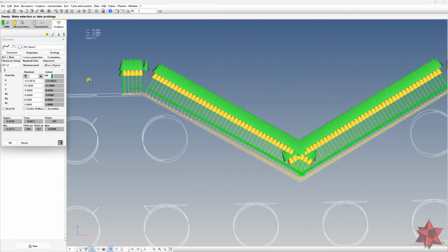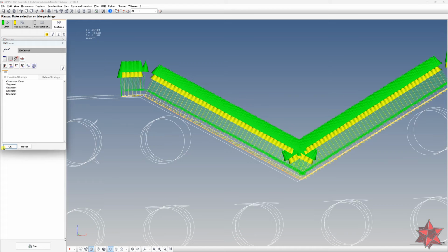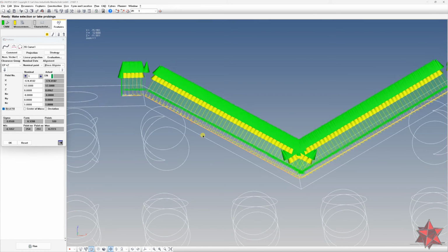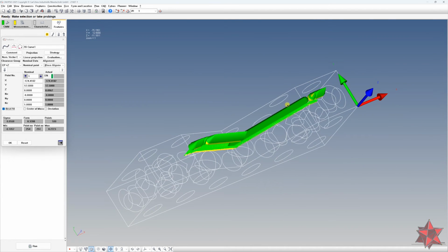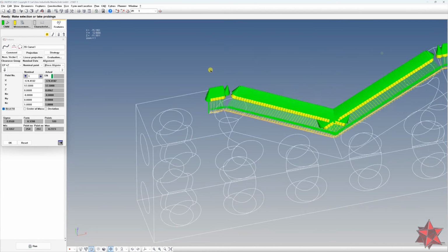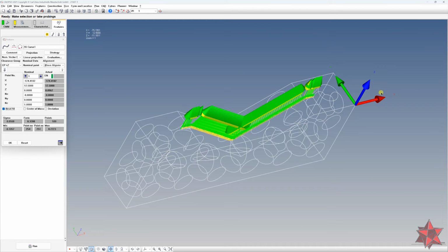Now let's see what happens if we do not do this. Okay, so let's leave it like nominal vector direction, right? Let's leave it like this. We have the same strategy like we see here that we did earlier. And of course we have to check this best fit, because it will take all the points and try to best fit them as best as Calypso can according to the nominals from the points and the origin of the alignment.